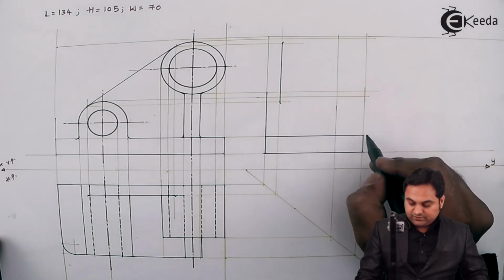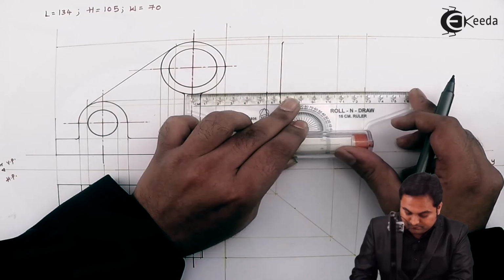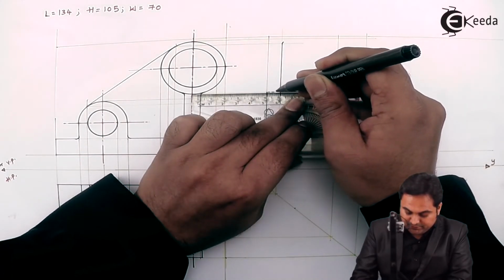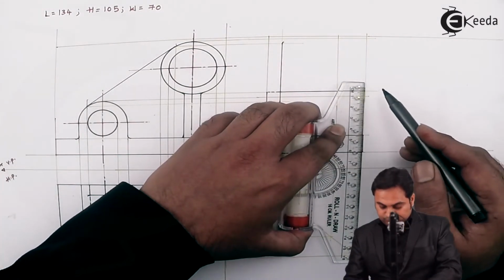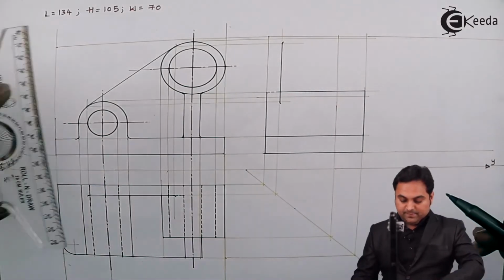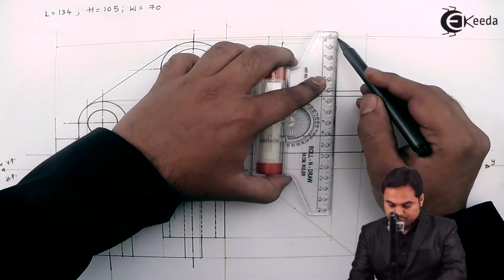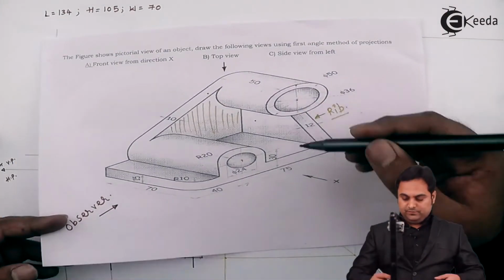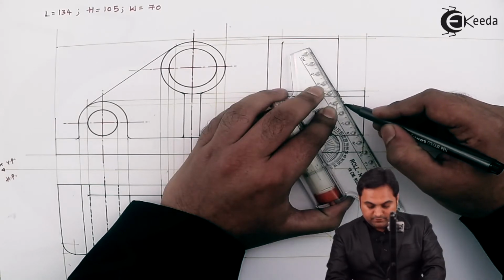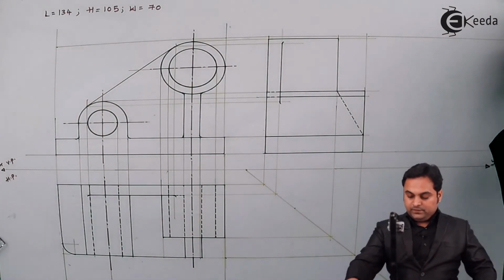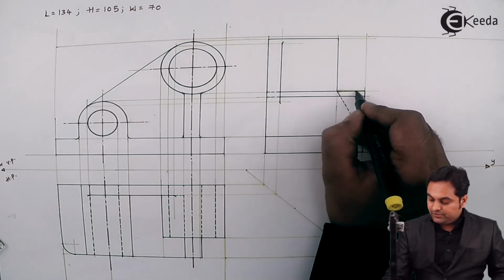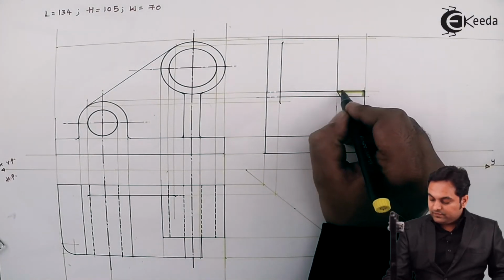Next, this is the semicircular cylinder having width 70 mm. And this much portion of the cylinder will be hidden. Then above this there is another cylinder whose width is 50 mm. Here this rib is also visible, so the rib will be connected in this fashion and the remaining portion of the rib will be hidden. Then here this much portion is not there, so this we can just remove. This portion is not there. This I am just eliminating.